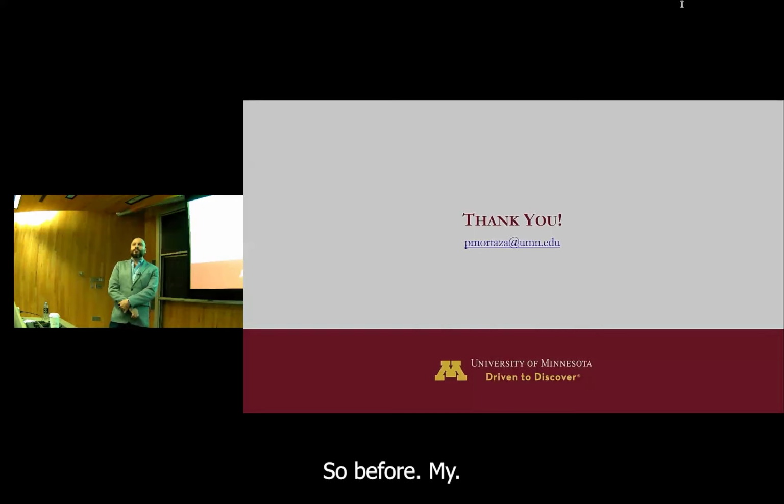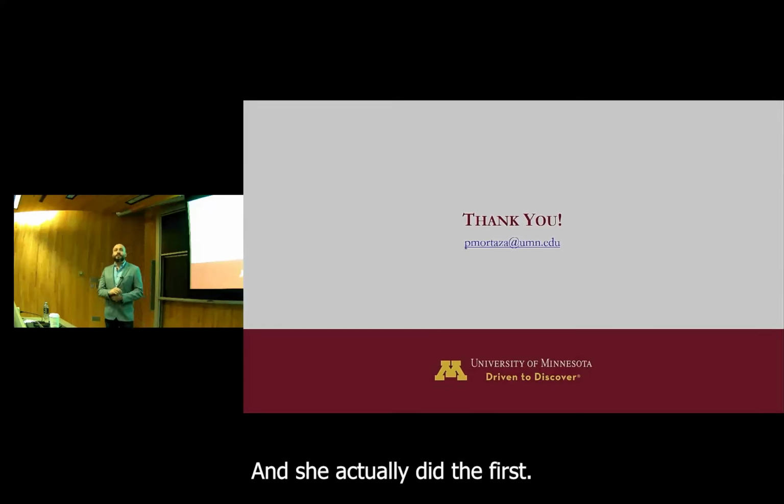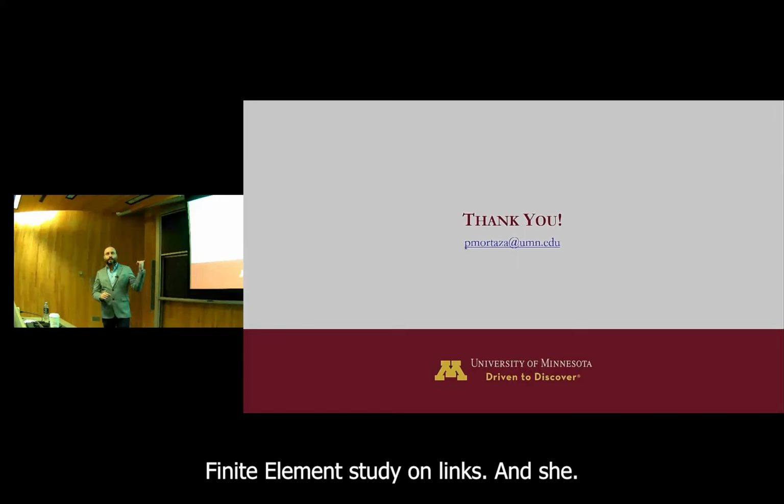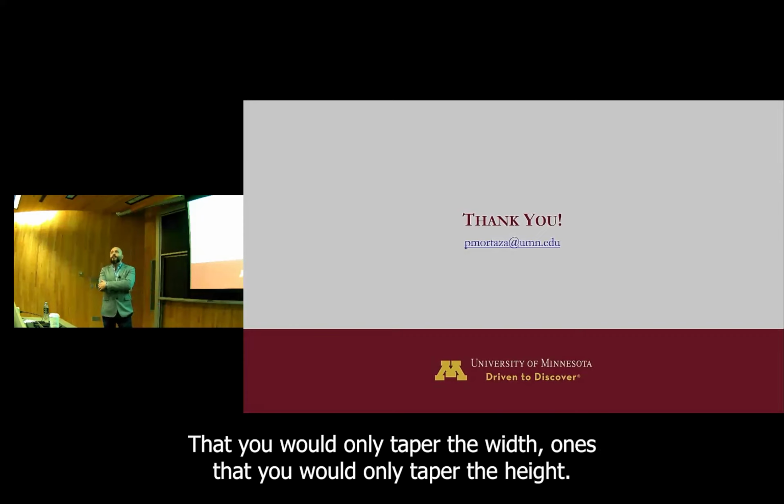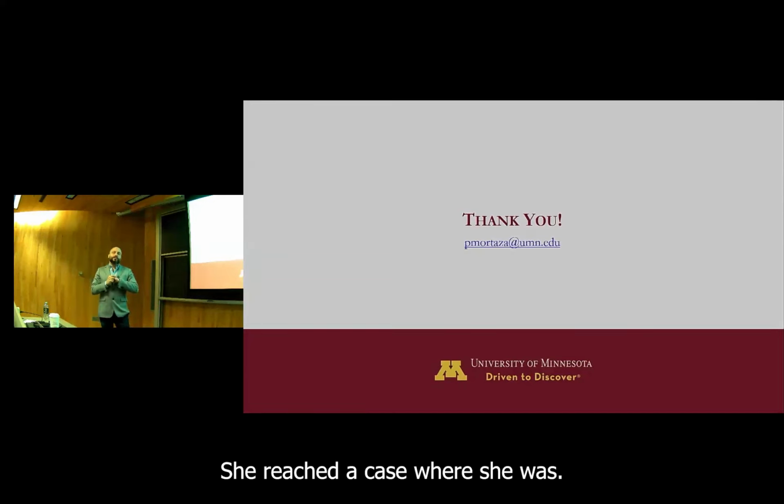That's a great question. Before my PhD, my advisor had a master's student, Kyla Tan, and she did the first finite element study on links. She looked at so many geometries: cast steel links with corrugated web, or with rings next to each other that would each yield, or ones where you only taper the width, or only taper the height. Eventually she reached a case where she was tapering one of those, but not the thickness.